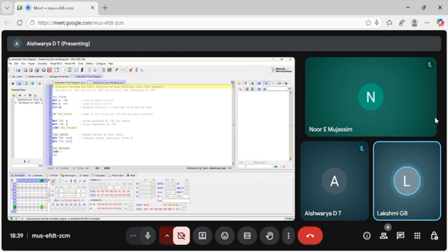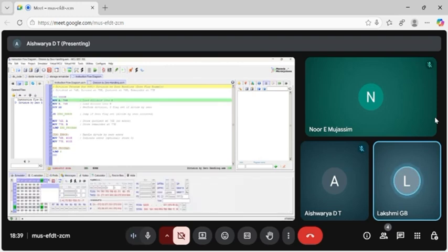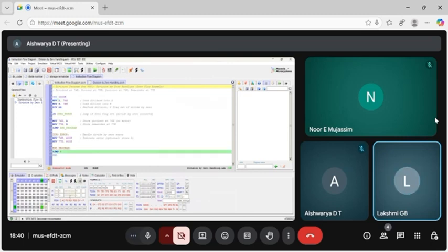Normal division example input: 74H equals 06 or 6. 75H equals 02. After execution, A quotient is 3, B remainder is 00. 76H is 3, quotient saved. 77H is 0, remainder. Division by 0 example input is 74H equals 6.